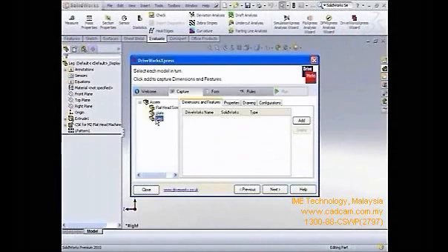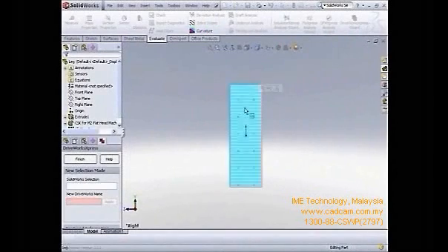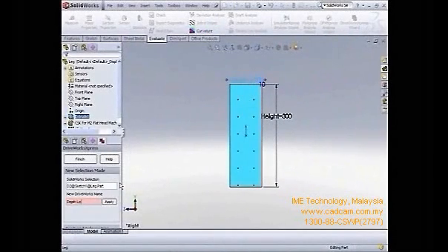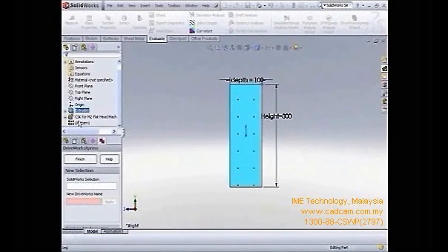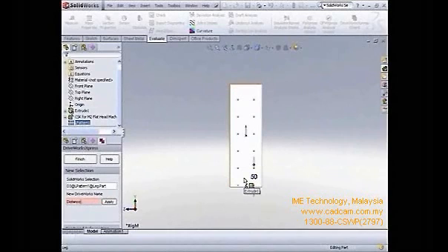Next, select the leg and click on the Dimension and Feature tabs. Select Add to load up the leg model. Capture the dimensions of depth, height, and thickness and provide a specific name using the same steps like before. Double-click on the Linear Pattern 1 in the FeatureManager. Capture the dimension that defines the distance between holes as well as the dimension that defines the number of holes. Load the drawing for the leg, following the steps before.